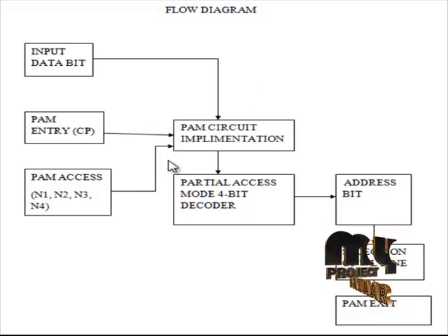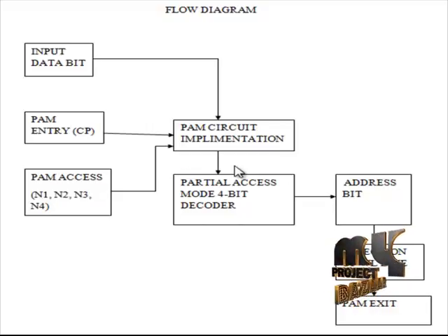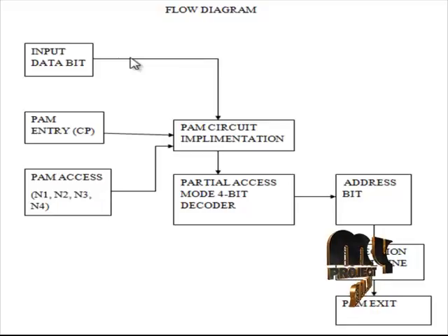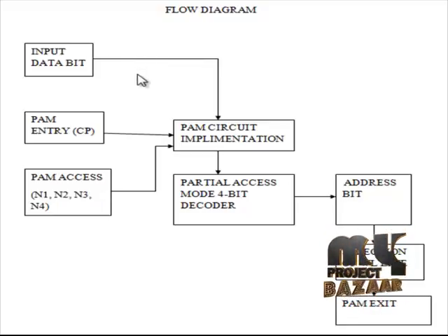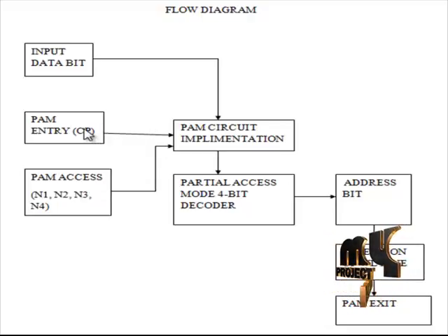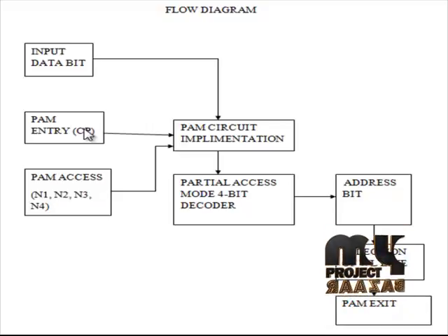One characteristic of the PAM is that it holds the data using 2 power n cells per bit to extend the retention time. The PAM entry operation indicates the conversion from 1 to 2 power n cells bit. This is simply a copy operation from the memory cell connected with 1 word line to 2 power n minus 1 memory cells connected with other word lines. This operation is simply achieved by the DRAM array structure.